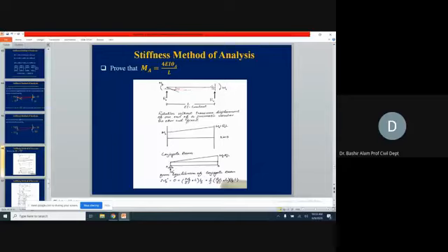And the reactions now, look, we are giving the general reactions. Now, we assume both in the upward direction, RA and RB. Now you can see it's general, we don't know. Otherwise, if MA and MB are in the clockwise direction, you should be having a balancing couple. But generally, we assume the direction. What will happen at the end? You will get a negative, and because of the negative, you can reverse the direction.